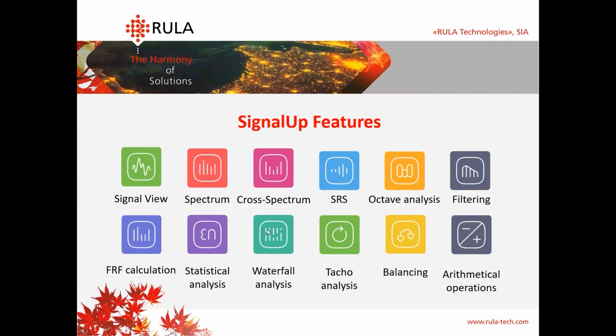Now let's talk about the analysis features. I will describe them during the show-up, but let's discuss them. In SignalUp, you can show the recorded or online signal using signal view. You can create cross spectrum, regular spectrum, and build shock response spectrum. You can perform octave analysis. Also, you can calculate FREF and make some statistical analysis to get more information about your signal.